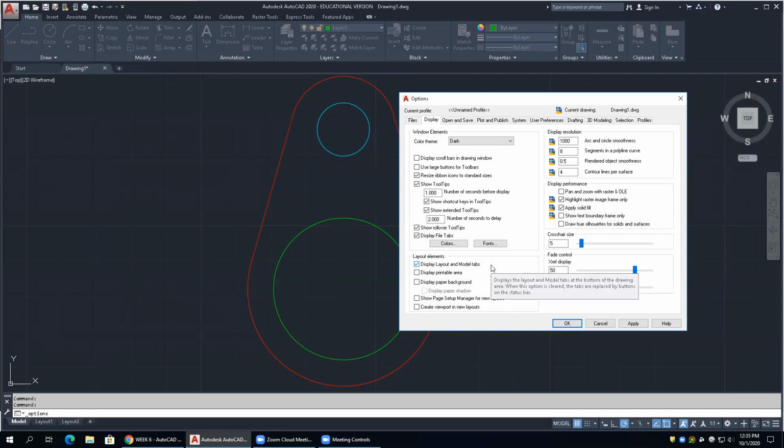So you guys that are working at home, listen to me. Anybody that's going to be working on AutoCAD at home, when you do this at home, those toggles are all going to be turned on, and your picture's not going to look like what we're going to see. Okay? So if it doesn't, you just have to go to options and turn it off. Okay? Because once you turn it off, it'll stay off. Okay? All right, so we're going to OK that.